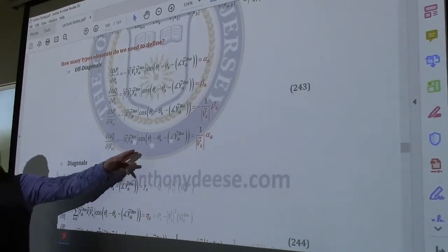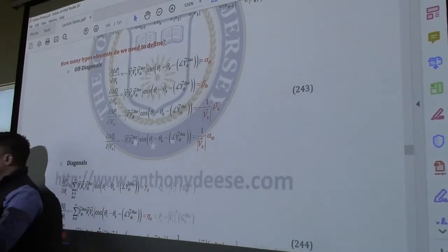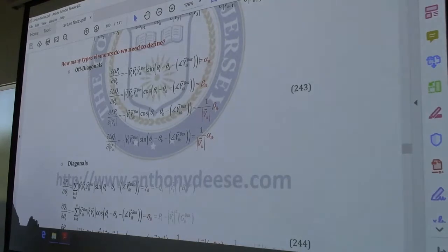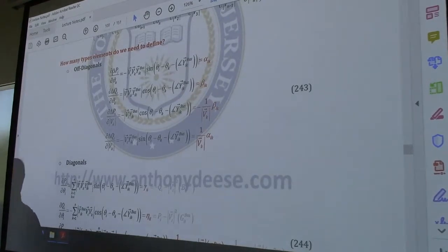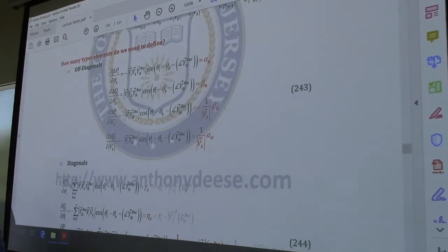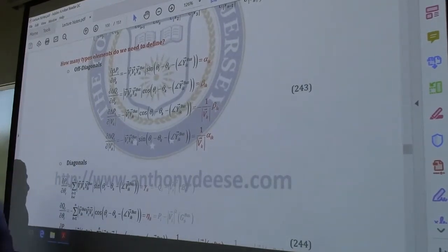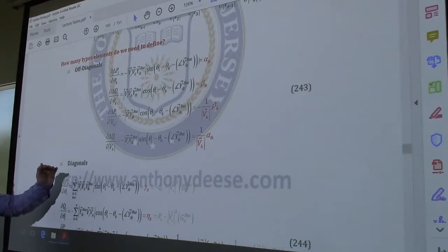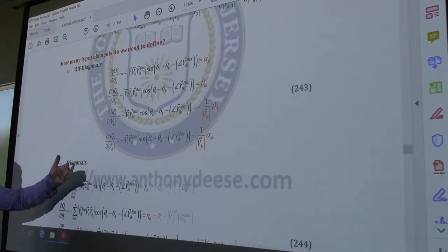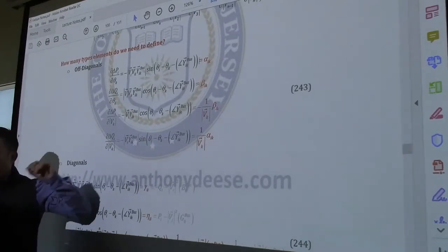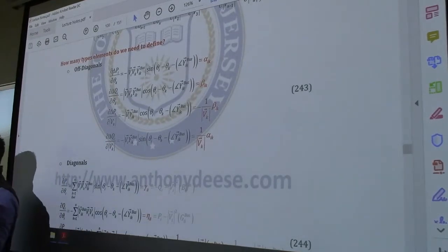The v's and the thetas will either be the initial condition or whatever the previous value was, right? You're always going to have a running value of all the voltage magnitudes and all the voltage angles. Your Y-bus matrix should be defined, etc. So without doing the derivative, the derivative's already done for you. You plug your values in here, and you have your off-diagonal values for the Jacobian matrix.